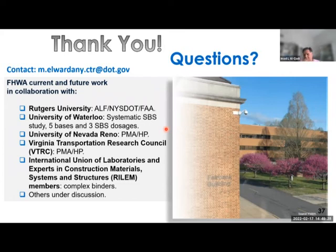Thank you again. Thank you, Dr. Ahmed. I totally agree with you. Those are very great points. I think in the DENT test, we don't have this effect that is coming from the geometry, because we run 3 ligament lengths and we apply a full fracture mechanics approach to capture the CTOD, which is supposed to be a measure that is not dependent on the specimen geometry. So the DENT test has this quality. ABCD is definitely going to be affected by the specimen geometry.